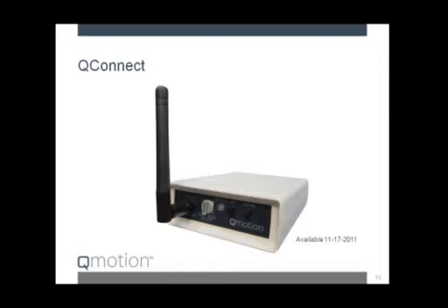It will also have dry contact, so it will have additional control capability. It will act as a transmitter just like our regular handheld units, just without buttons. So in the case of this device, simply provide the programming instructions and wiring details to the installer or the integrator with the system, and they will put the device anywhere that the signal can reach our shades. The device is one way and can control as many as 16 shade groupings.